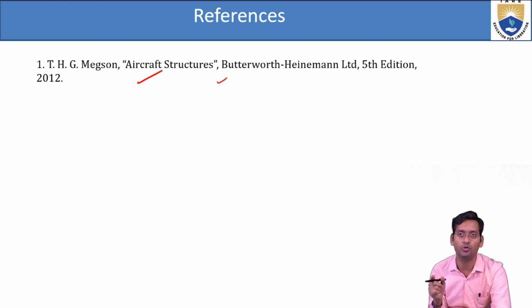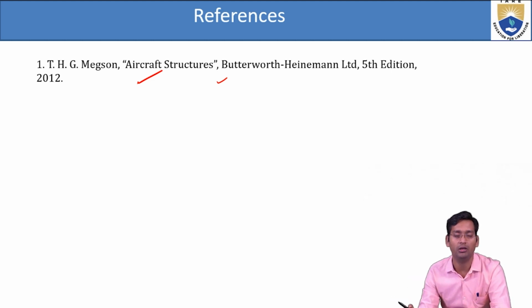Once you have the fictitious force, multiply with the load, differentiate with respect to PBF for B and PDF for D. Find, then multiply according to the formula. Just add, divide by AE. You will get the solution.